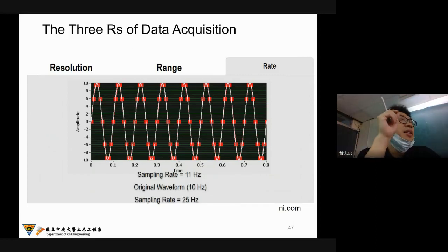This means that if you have enough sampling capacity and also disk space on your computer, I would encourage you to use at least 10 times the sampling frequency. It means that you may have a much smoother signal.